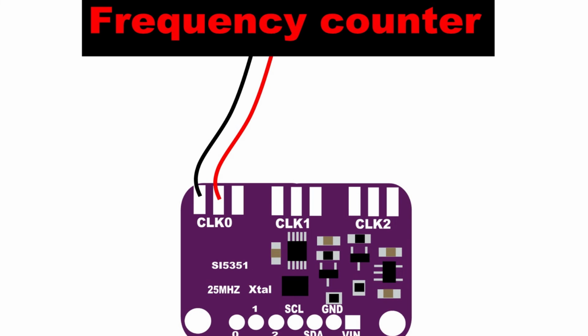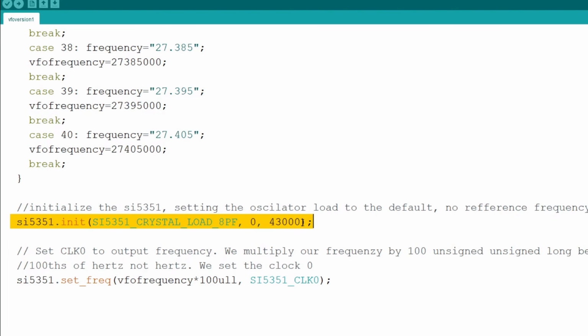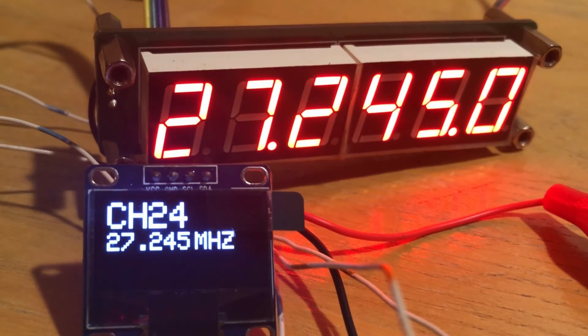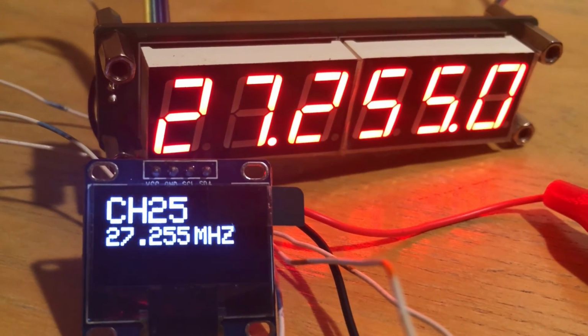I started with the example code that came with the EtherKit called Calibration. I connected my frequency counter as shown and tested the sketch. I used the correction value I came up with by running the calibration sketch and attempted using it in my sketch. It was closer, but still not good enough. I changed the value hard-coded into the sketch and re-uploaded it a few times until I had these results. It is now a working and fairly well-calibrated signal generator.